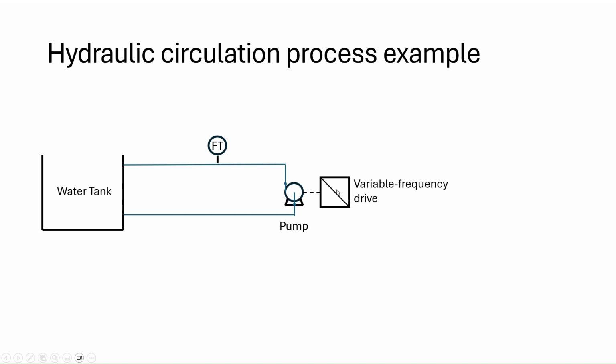Then if we continue until the pump, we have of course the pump itself, and we have the VFD, which is controlled through the PLC. These signals differ, but let's say we have a 0 to 100% signal. We could use analog output for that from a PLC, from 4 to 20 milliamps, for example. And that will be a signal here. There's of course some feedback signals as well from the frequency drive, or error signals and that, but we will leave it just very basic.